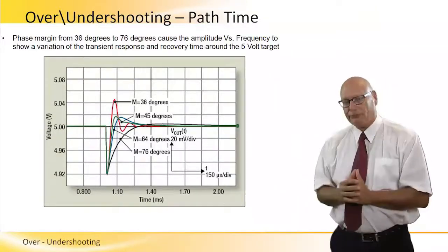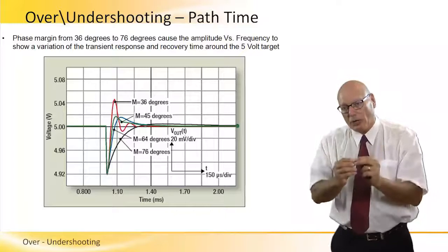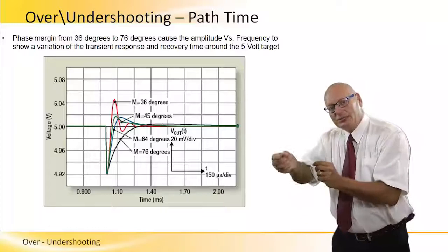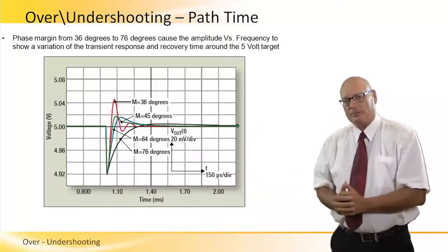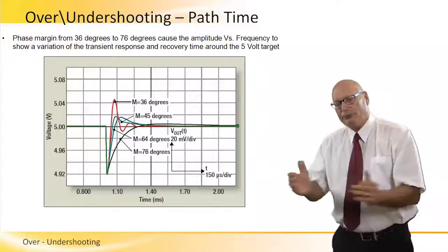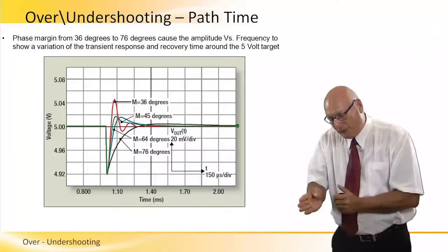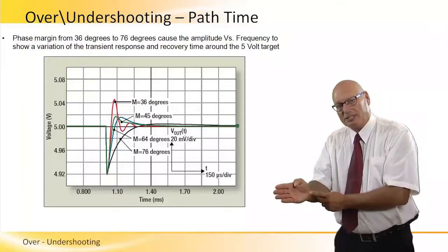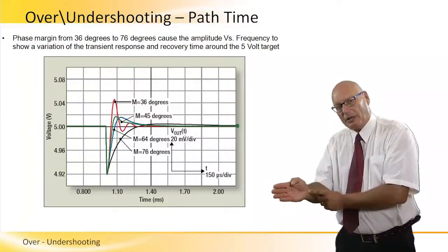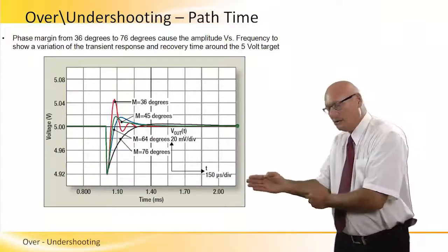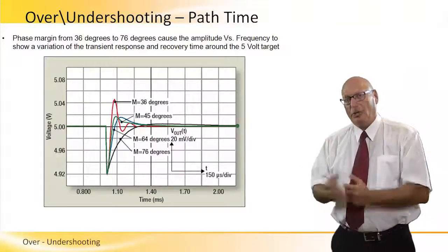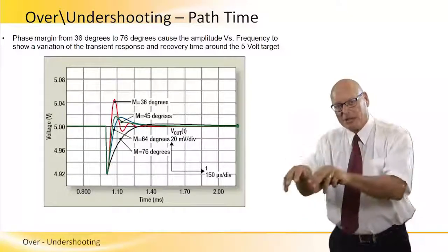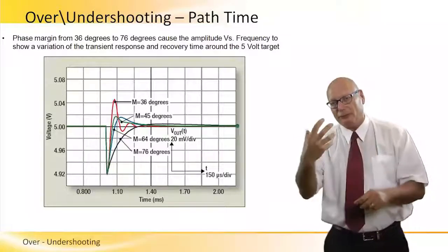And in this particular graph, this is how we can control what the degree will be at any time within that range. So from 0 to 1.4, we can be at 1.15 at 45 degrees, and 1.2 milliseconds later, we can be at different degrees and get to the target. Using Q that was given to me by tables when I plugged in the torques, acceleration, deceleration, physical parameters.